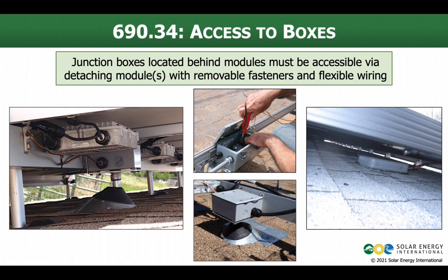So this is something that happens all the time on roof-mounted systems. And it's also something that kind of differs from a lot of other people's expectation of what the National Electrical Code makes you do. In general, we're not allowed to, I'm making air quotes, bury boxes, make them so you can't just get right at them. But here we're allowed to. It helps with the aesthetics of an array. Put it behind the array. It makes it a cleaner installation.